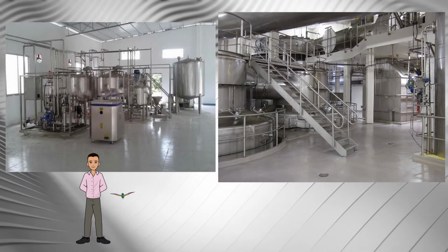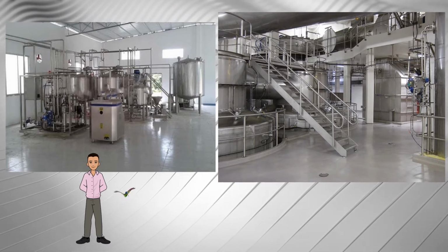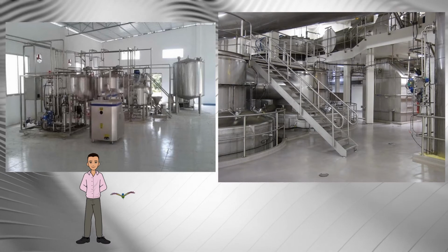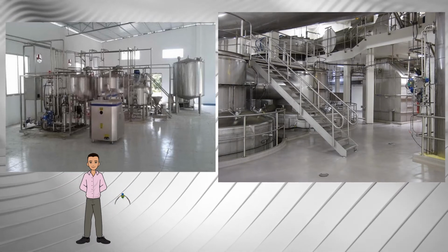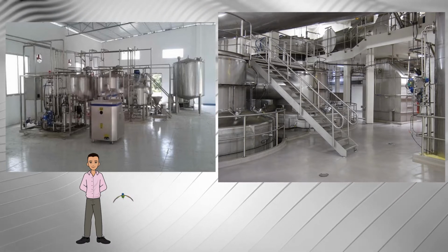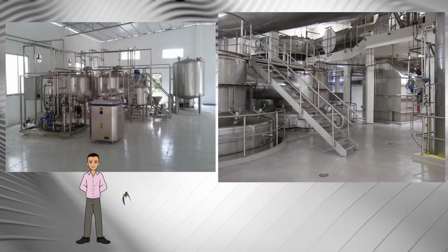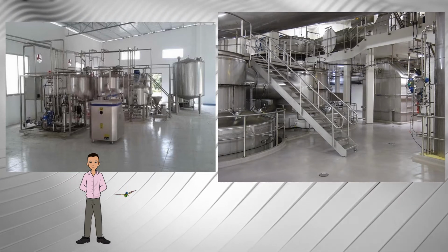Milk powder contains lactic acid, which is moderately aggressive, particularly to flat roof coatings such as asphalt and felt. Consideration of the durability of the roof is therefore required. Internally, a biologically clean environment is required in order that the plant complies with process regulations.